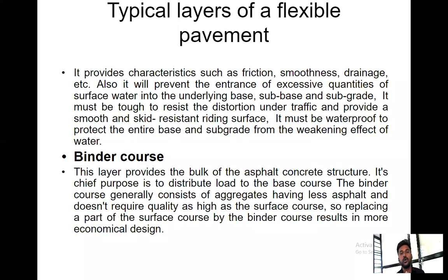Then it should have proper drainage. The water should not stay on the road. Also, it will prevent the entrance of excessive quantities of surface water into the underlying base and subgrade. It must be tough to resist distortion under the traffic and provide a smooth and skid resistant riding surface.